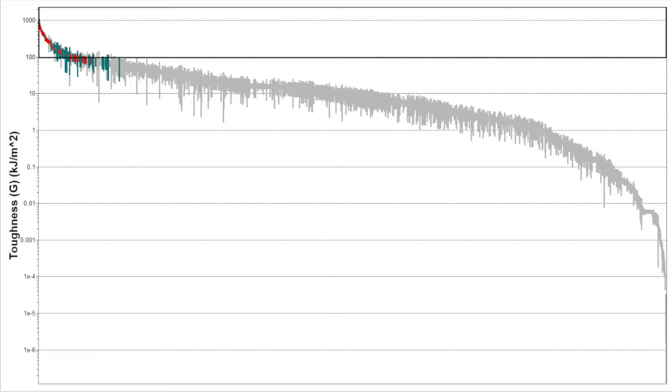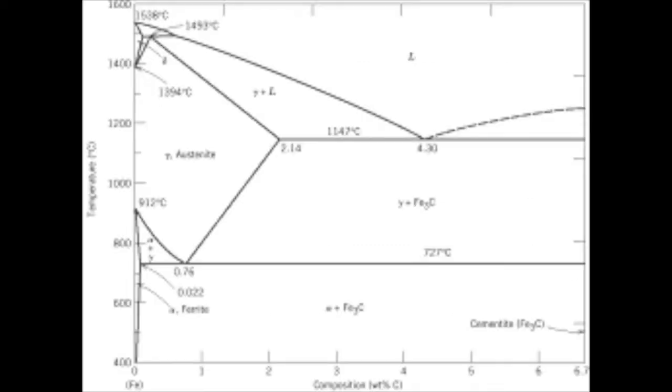High toughness is preferred because it allows the shackle to be unaffected by impact forces it sustains when people try to break it. Based on the requirements from the previously mentioned design specifications, it was determined that SAE 8630 steel alloy would be an appropriate material for this application. So an oversized SAE 8630 hot rolled stock bar would be received from the manufacturer.